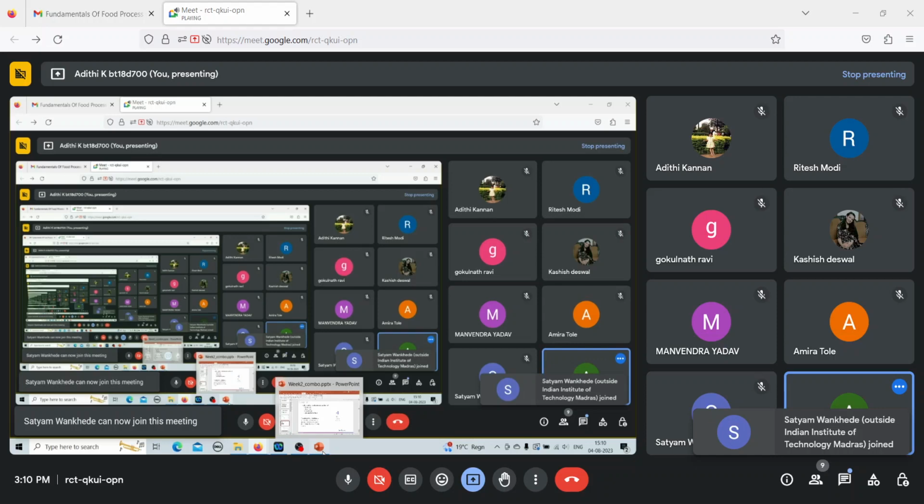But one thing that becomes difficult is, since the region between these is very small, there is a good chance that the temperature would be very difficult to control. You'll have a lot of shear, you'll have a lot of friction that will increase the temperature of the system. The moment temperature increases, your viscosity no longer remains constant. It will keep changing with respect to temperature. So maintaining constant temperature is a challenging part in these viscometers, but it is very important to maintain the temperature in order to get accurate measurements.